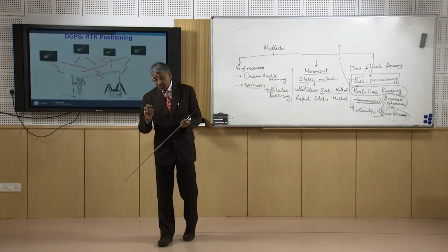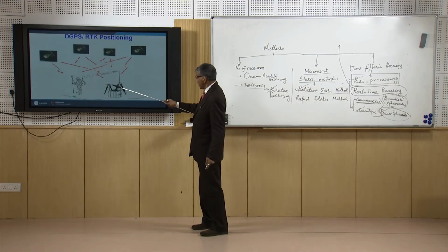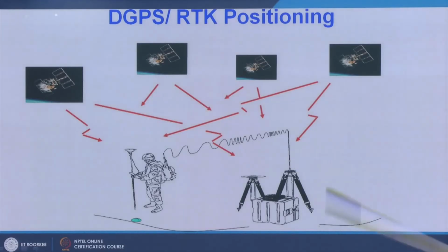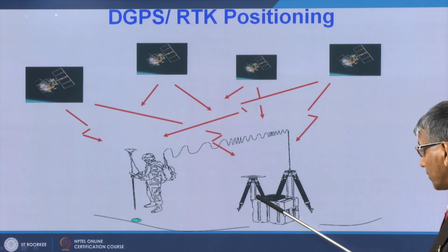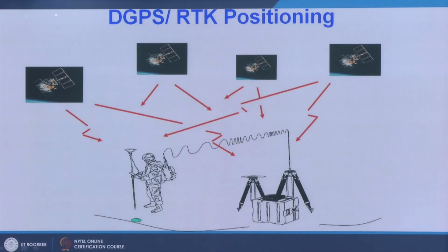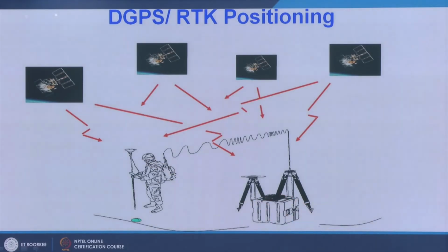So, it will know what is the error that is arrived at from the GPS signal. At present it is working. Now, near to this, suppose another point whose location is to be determined, there we will set up the instrument.